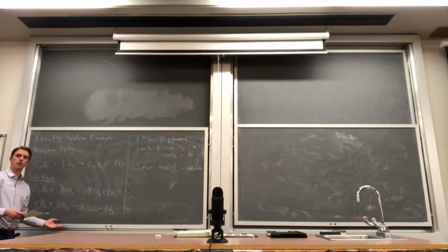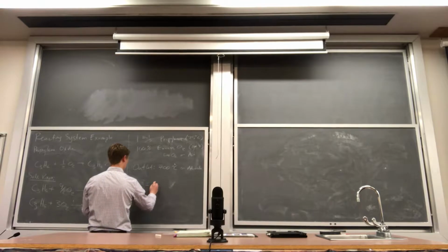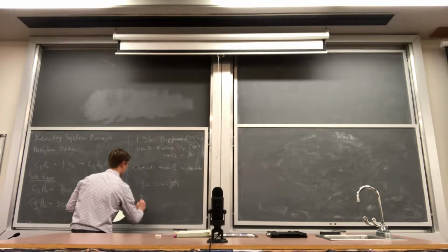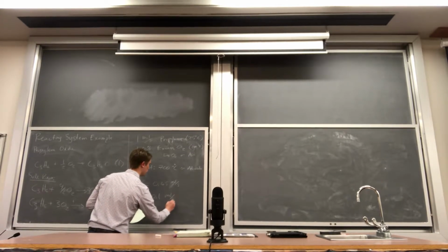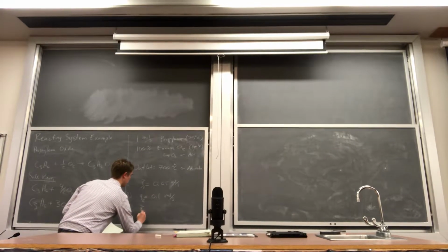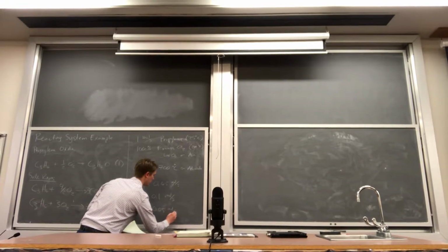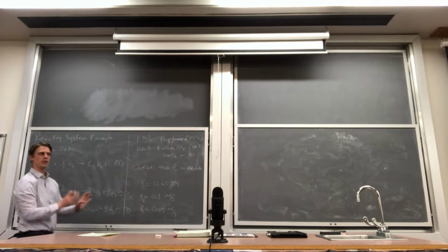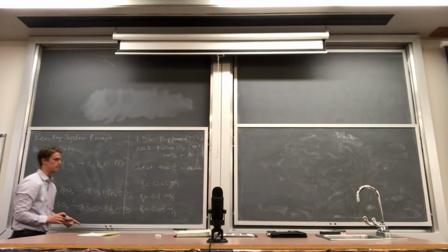So we need some information on the material balance before we can attempt to solve the energy balance. So I'm going to call extent of reaction 1 as 0.65 moles per second, extent of reaction 2, 0.1 moles per second, and extent of reaction 3, we'll say 0.05 moles per second. This is significantly more complex than any of the homework problems that we have on this week's assignment.